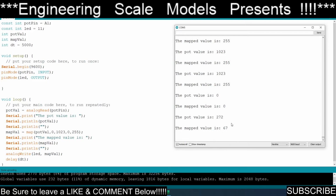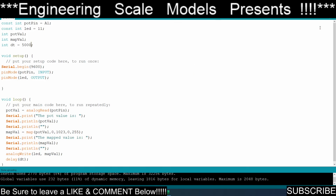So I have to turn it, wait, turn it, wait, turn it, wait. So it's not getting updated all the time. What you can do is put this reading of the potentiometer in a software interrupt, and it will constantly read the value of the potentiometer, and then the program will use it as it lights up or cycles through something multiple different ways. Now let me show you how to do a software interrupt.